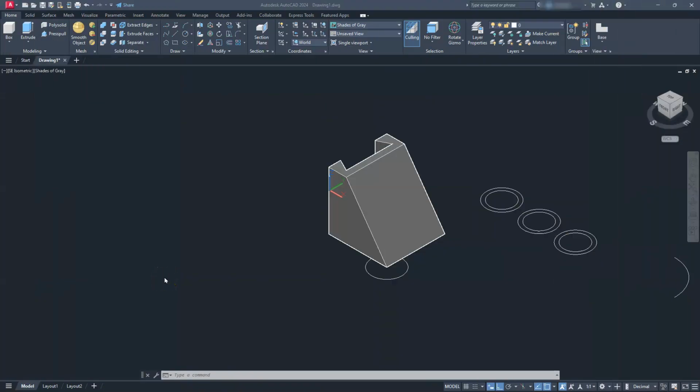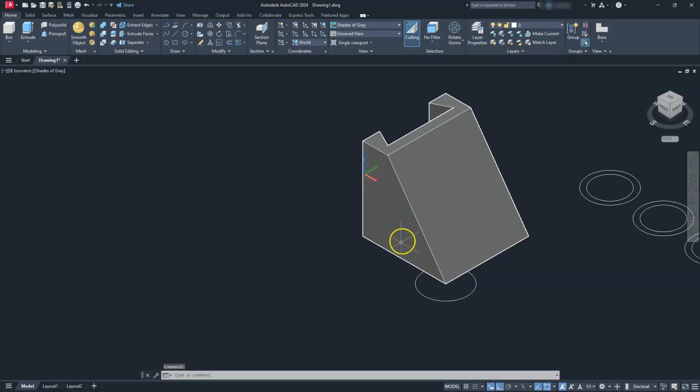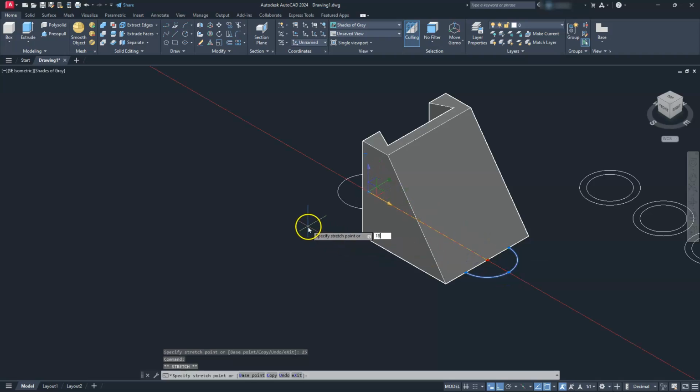Okay, so we can decide to do this in two different steps, right? We can move it one direction and then come back and move it again if you want to move the gizmos, or we can move our UCS. We don't happen to move our UCS on too many occasions. This one, I'm just going to show it to you in both different ways of doing it, right? If we use the move gizmo, and this is going to be step number one, let's go ahead and select move gizmo. What I have to do with this one is just select the circle, and then you're going to select the axis that you want to move it on. I want to go this direction, 25, and then I'll select the red axis here, and then I'll drag back this way and type in 18.1. So that's one way that you can locate that.